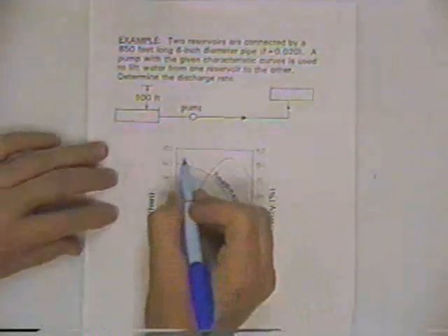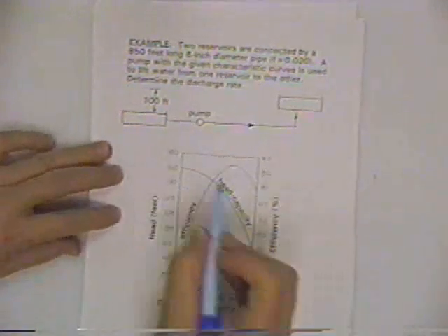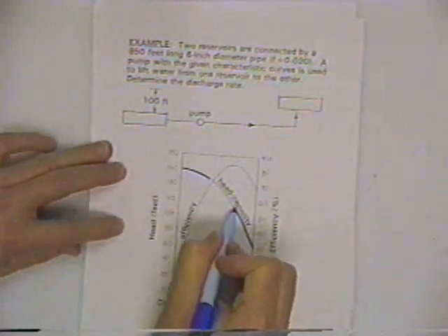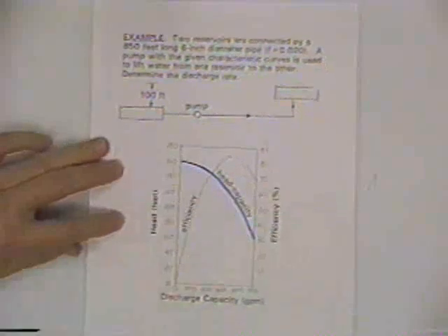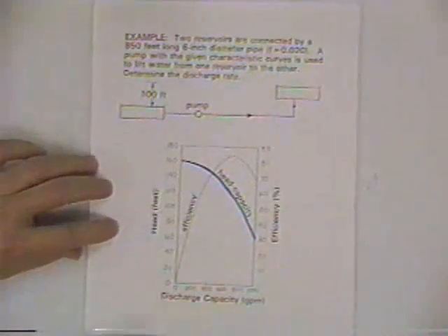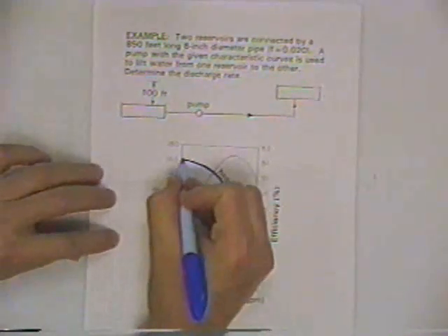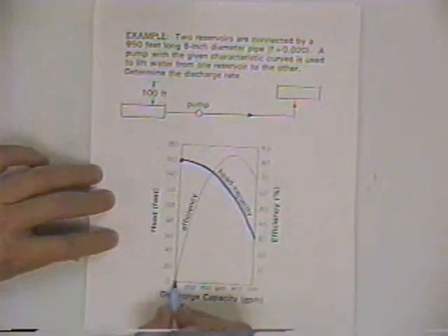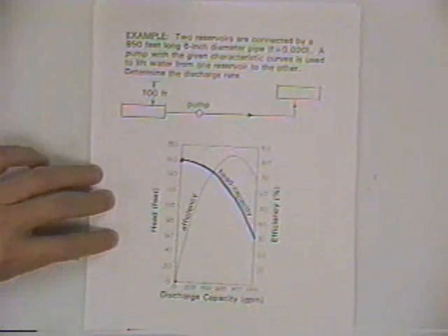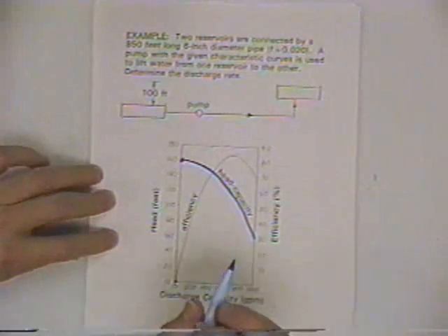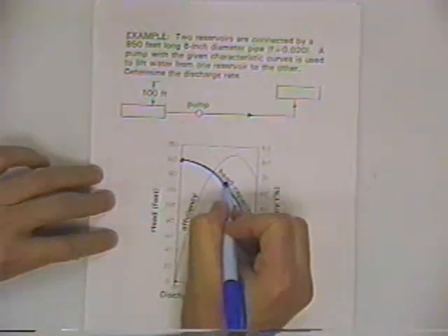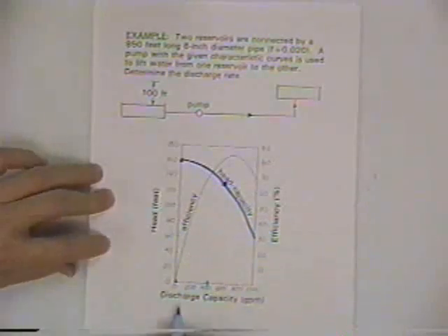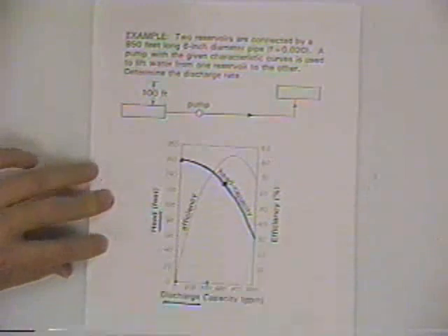And so what this curve says, and this would be given in the problem because it's for a given pump, is determined by the pump manufacturer. And it says for this given pump, if this pump has to overcome 160 feet of head in this example, the discharge rate's 0. That's it. But if there's not so much head, if the head decreases, it can pump greater discharge rates. So we're looking at discharge versus head.